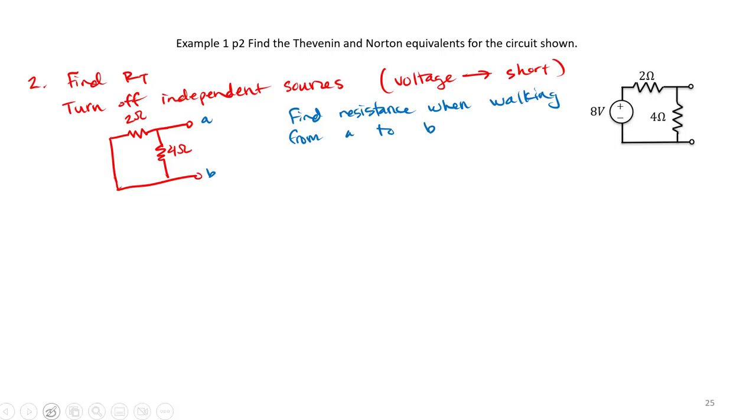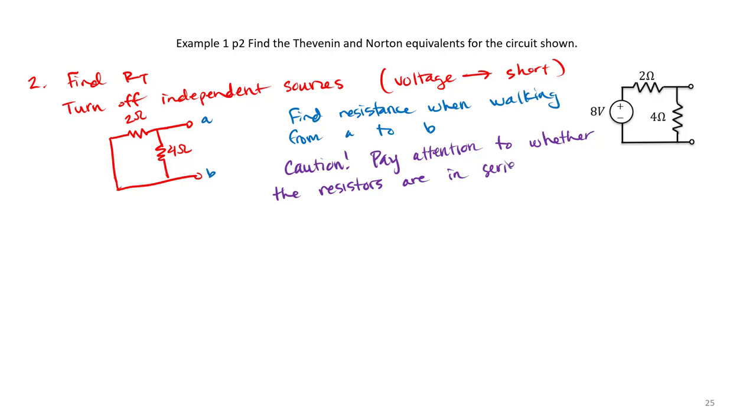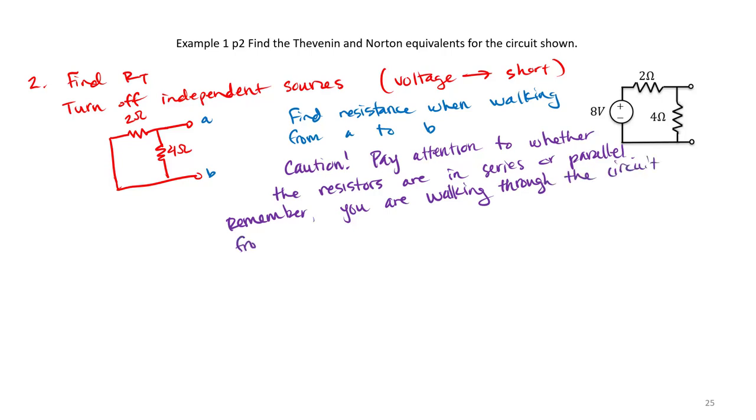So here's another area where you need to be careful. Pay attention to whether the resistors are in series or parallel. Remember, you are walking through the circuit from one open terminal to the other.